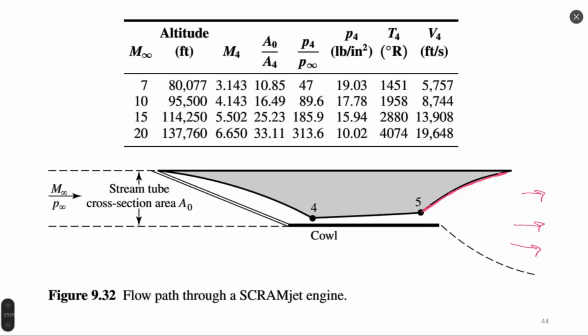Then we see the Mach number corresponding to this altitude at 0.4. We see that Mach number 4 always remains supersonic. Okay, but then it decelerates. After several or many reflections from walls, it decelerates to sonic or subsonic. In some cases, it does not decelerate to subsonic flow and remains supersonic, and such combustion is extremely difficult to organize technically. It's called supersonic combustion.